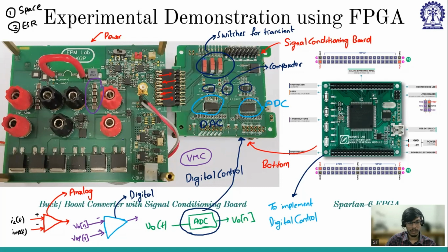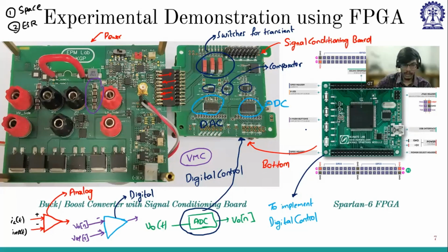So you mean, sir, you're saying then the SMD is better? Yeah. Sir, this SMD has higher ESR, right, sir, compared to through hole of the same value capacitance? No, see, if the trace length is more, it will have a higher impedance path. So SMD will have lesser parasitics compared to through hole.